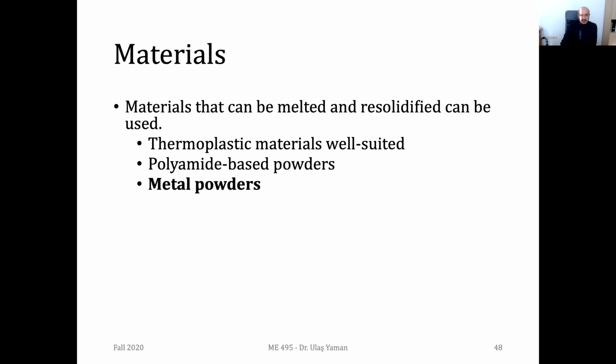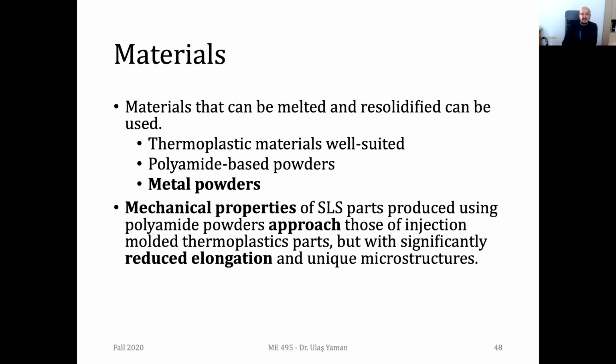And we discussed these issues, and we know that after the melting, we need to have solidification, and it's quite difficult for the metal powders. The size of the grains and their elongation directly affect the quality of the part. Whether you have elongated microstructures or circular ones, they highly affect the quality of the parts you want to print.